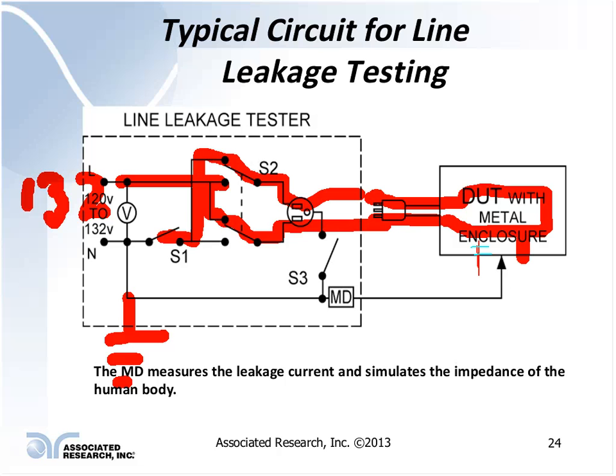And what is a capacitor? It's two conductors separated by an insulator. So we're testing this insulation. We're measuring the leakage current on this side of the line, which is sitting at a 120 volt potential. So all this is in parallel, and all that current is flowing back through my measuring device, trying to get back to my reference neutral side of the line, which is ground reference.